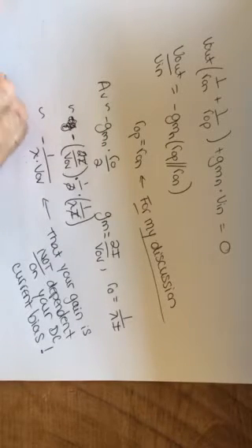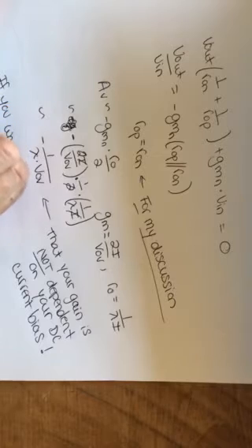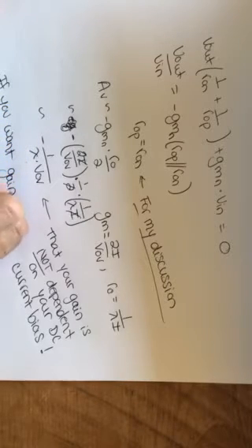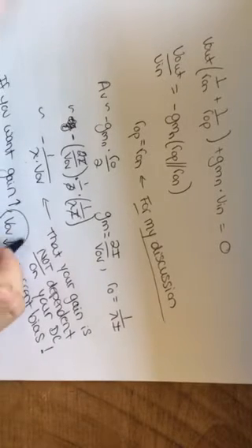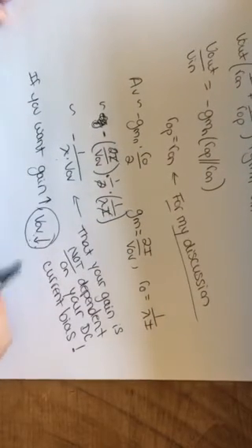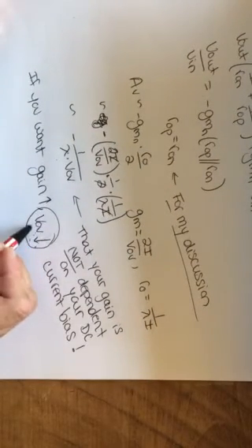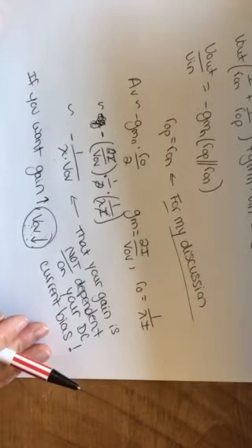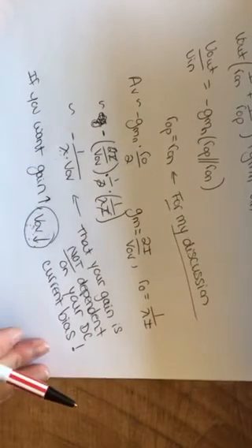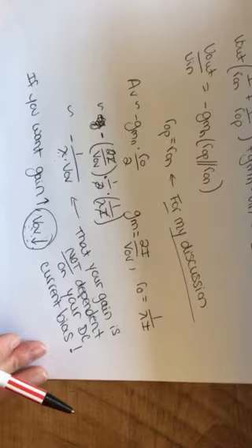So if you want the gain to go up, you need to make your VOV smaller. Okay? And in your lab, this VOV was given to you. So you fixed this VOV at an actually pretty small value. 0.1 volts is a very aggressive VOV, meaning a very small VOV. And so by fixing this VOV, you have in essence fixed your small signal gain for a particular process and a particular length device. Your length was also fixed at 300 nanometers.